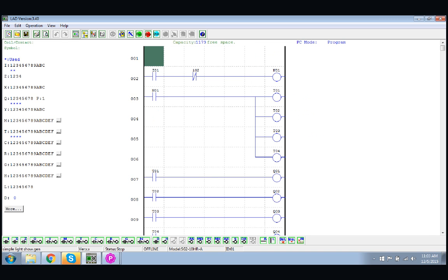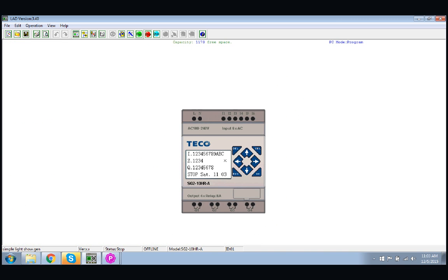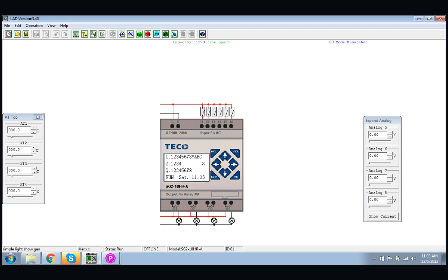So let's view this from the actual machine view, and we'll go input 1, and then if we count 1 second, 2 seconds, 3 seconds, 4 seconds, we can see that all of our outputs have activated. And now if we push the button, normally closed, it opens the circuit, and bam, they all fall out. So this is really cool.